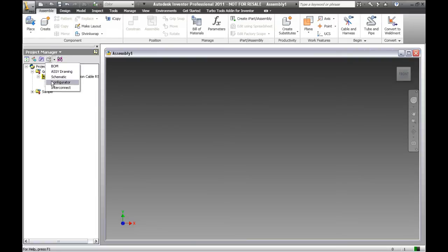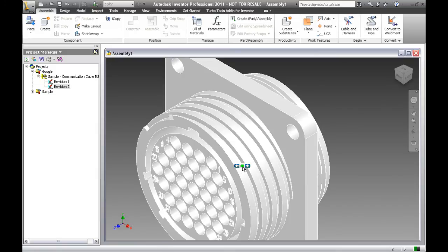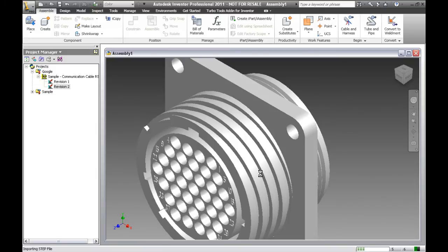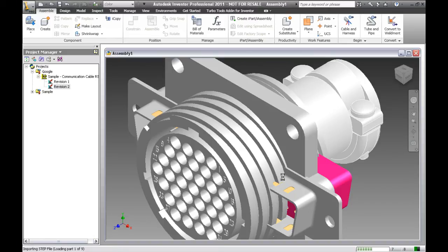For example, you can access the 2D Workspace pull-down menu and execute any commands from this menu without CablEquity running. Clicking on the 3D Models Transfer button will transfer all 3D solid models for all components which have been selected for this design in CablEquity into Inventor. Components will transfer individually, and you can see them appear in this panel. When all components are transferred, each component can be moved and placed in any location of your 3D model layout.